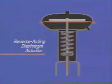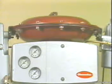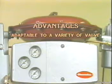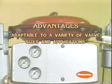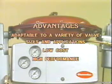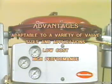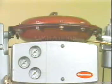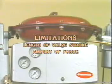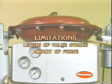the spring to compress. These types of actuators have a number of advantages, including their adaptability to a wide variety of valve sizes and applications, their low cost, and their high performance. However, these actuators do have limitations. There are limitations on the length of valve stroke that can be obtained, and there are limitations on the amount of force that can be developed with a flexible diaphragm actuator.